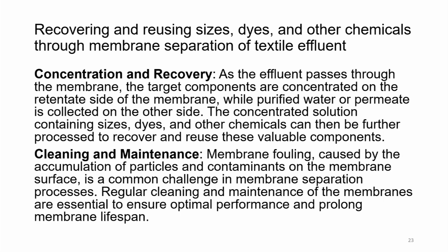Concentration and recovery. As the effluent passes through the membrane, the target components are concentrated on the retentate side of the membrane, while purified water or permeate is collected on the other side. The concentrated solution containing sizes, dyes and other chemicals can then be further processed to recover and reuse these valuable components.